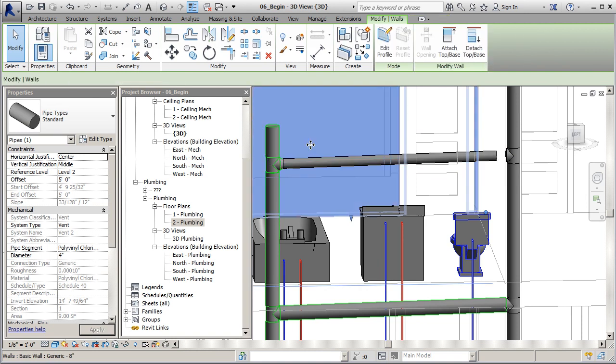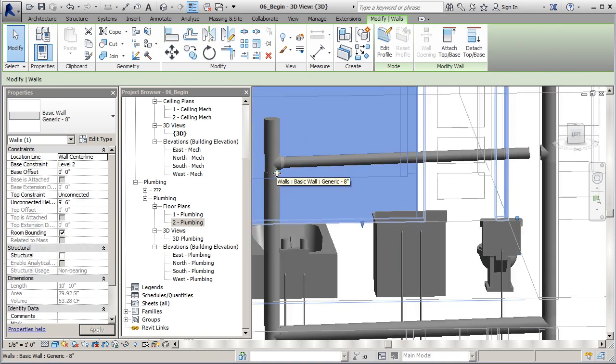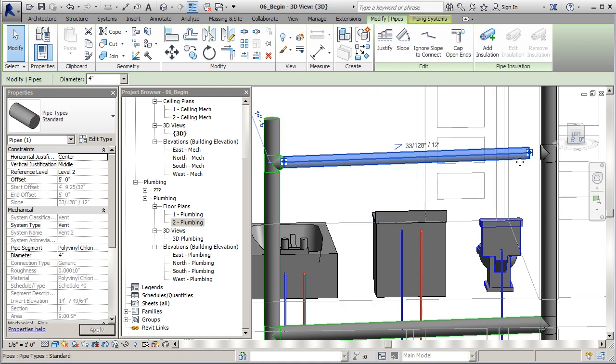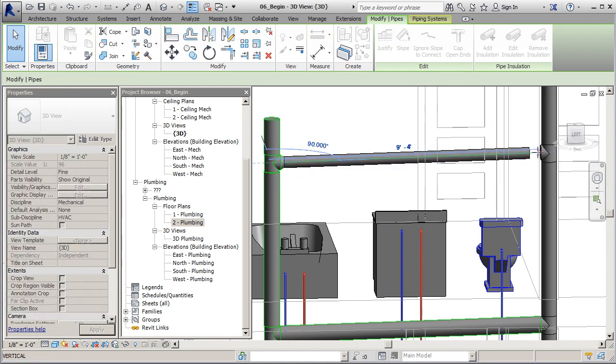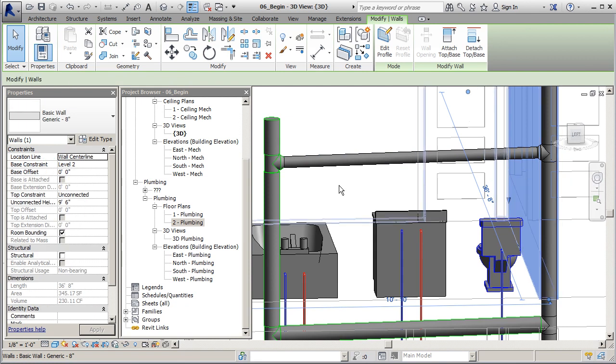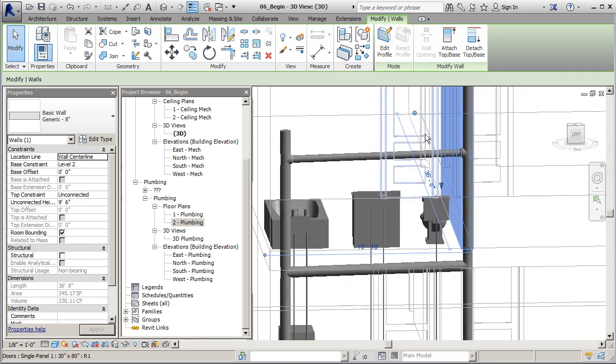And you'll notice it is connected properly. You'll see either a transition piece, or you'll notice a slight pause in Revit because it's thinking and making its adjustments to get these pipes connected. So those are two good ways that you'll know what's going on. You'll see that there. Again, you'll notice a slight pause, and you also notice my transition pieces connecting nicely into the connector there. So we're in good shape.